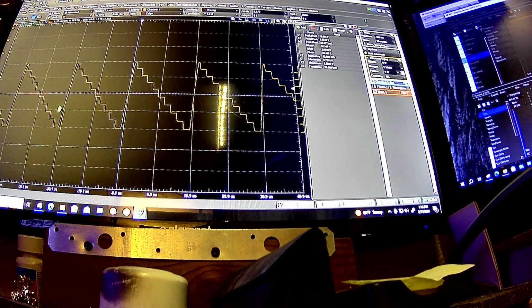That's why you have this little slope here that's not vertical. This is the smoothest you can do, using all those 10 samples from negative Vmax to positive Vmax. So that's as smooth of a waveform as you can make at 50 kilohertz with a 500 kilosample DAC.